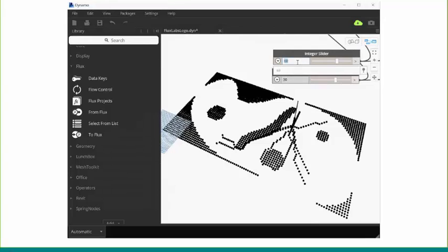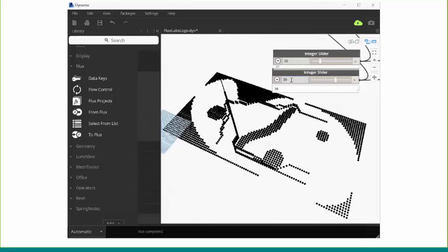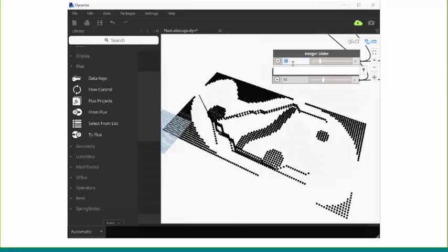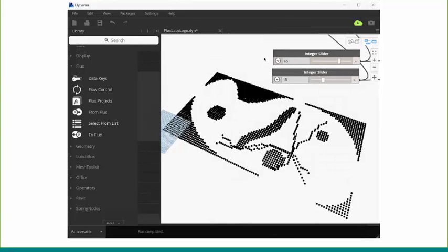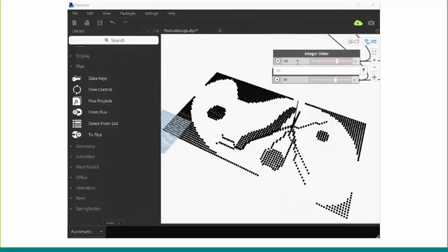And so you can see here, all I'm doing is changing my start point for the pathfinding. So it sends that data up to Flux. Flux recomputes the shortest path and then delivers that back down to Dynamo. And so I'm showing this at the moment as a set of points, a chain of points, but there's no reason you couldn't just then redraw that as a polyline. There's no reason why you couldn't even just have this being drawn in Excel. Again, it's just data at the end of the day. Let it be represented however you want.